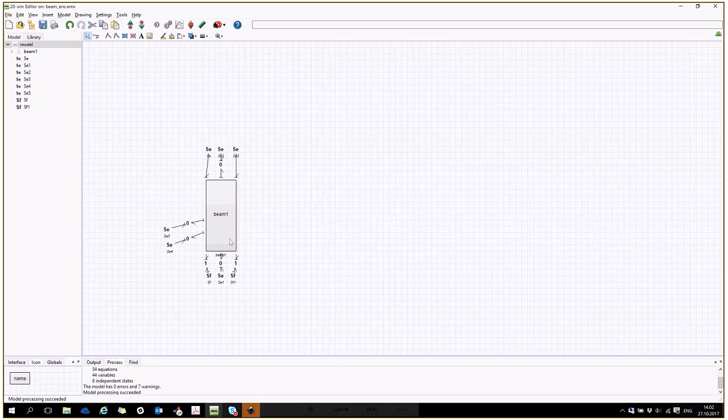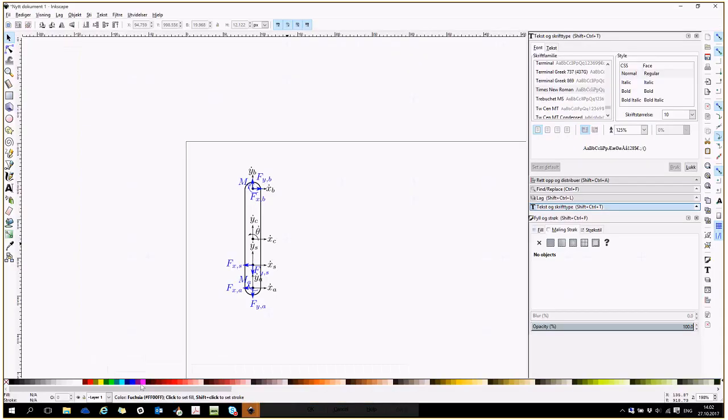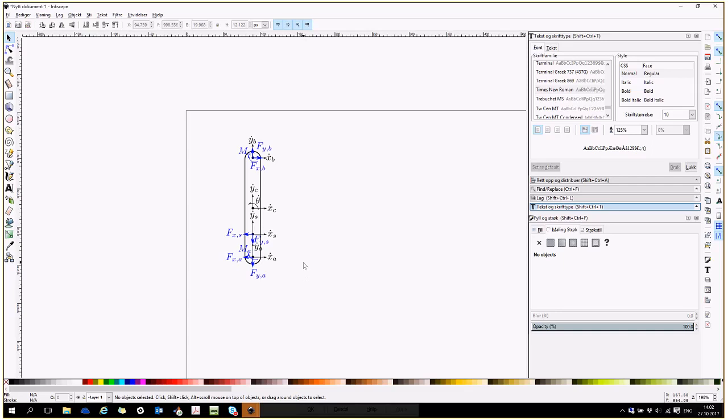And then the first thing you have to do is define your boundary conditions for testing. So in this test, I use my beam, which is modeled in this way. The boundary condition for testing is to fix this A point. So this is a fixed point and freely rotating.